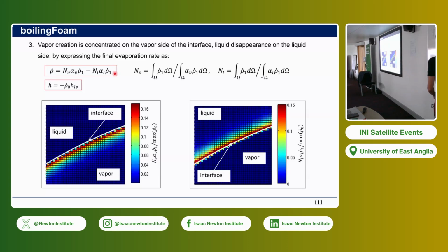Physically, you want to have a sharp change in velocity over the interface. So some people in Basilisk, but also in Paris Simulator, the code developed by Professor Zaleski, have implemented some specific method to preserve this sharp change in velocities while also preserving stability of the method.